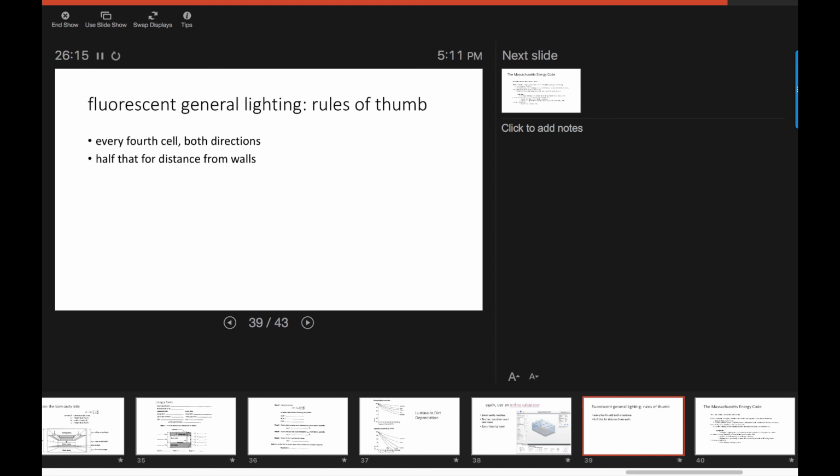And lower ceilings, obviously, you're going to have to use low glare fixtures, which are less efficient at getting light out of them. But that's a general rule for fluorescent, what are called troffers, those boxes up at 2x2 ceilings. With the advent of LED troffers, they're meant to be low glare fixtures that replace these fluorescent ones. For now, the rule of thumb is about the same. Okay.